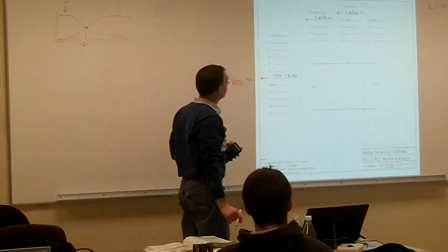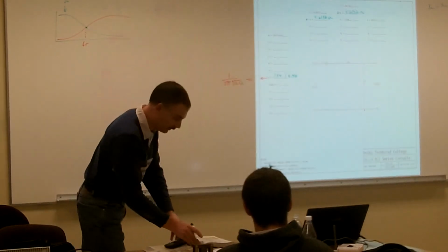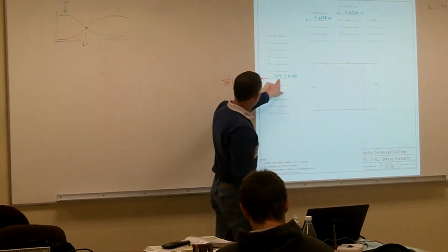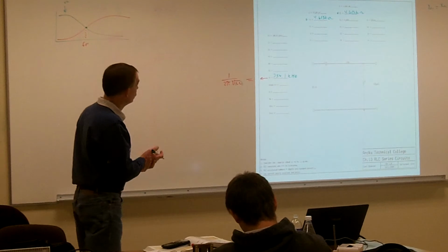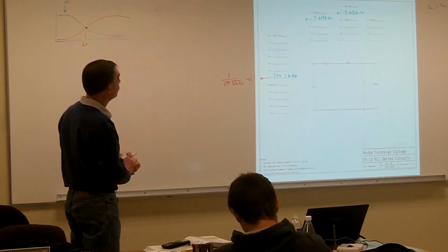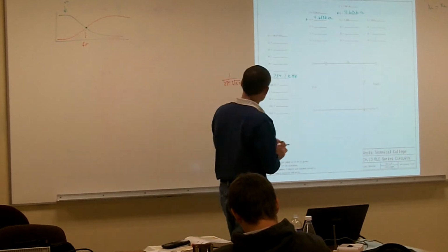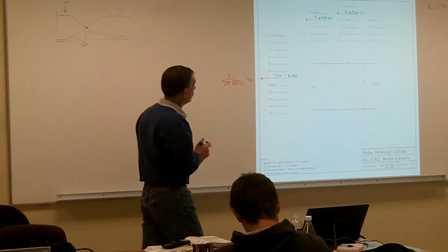So we can just calculate out our capacitive reactance using 2 times pi times our frequency of 734.1 kilohertz times our capacitance. Do the inverse of that and you should get 4.613 kiloohms. And once you know that one, and since we know that we're at a resonating frequency, we know automatically that X of L is going to equal the same thing.